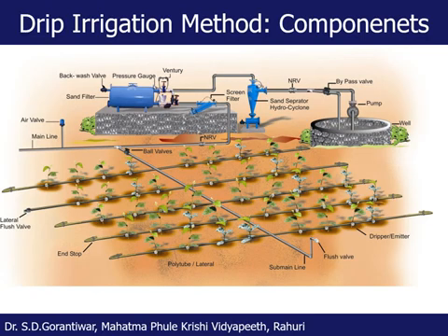As you see, there is a wetted area around each dripper. Then these drippers are mounted on the lateral, or inserted on the laterals at a specified distance. In this particular scenario, there is one dripper per plant, but this may not always be the case.